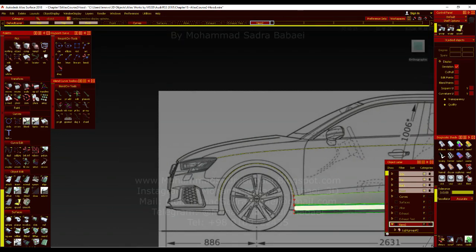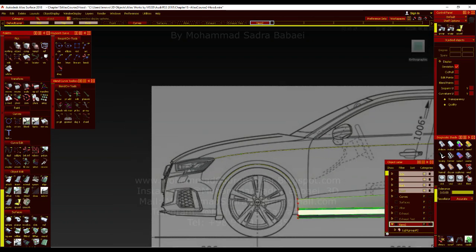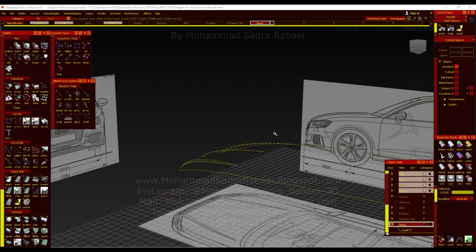Wireframe based modeling is what we are going to do, creating the curves at first, and after that we're gonna use the square tool, rail tool or freeform blend, or a little trim and draft to create our surfaces.